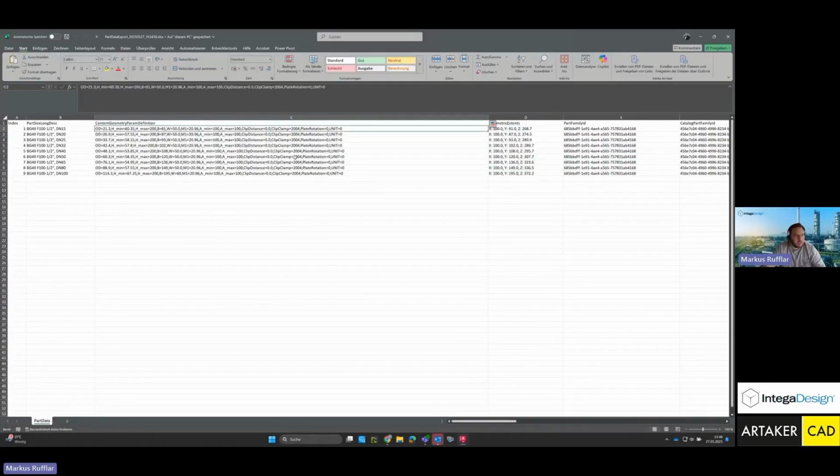I'm not exactly sure. Here, we don't have a length parameter, but imagine you have an L parameter here, maybe for a fitting. Now, everywhere it says 300, 350, and so on. And so, here the X parameter is exactly the length. Then you can quickly check here, okay, everything's 100, 100, 100. Entered here is also 100, 100, 100. And you already know, since these are ultimately the box's dimensions, from draw bounding box, these are the general dimensions of the entire component.